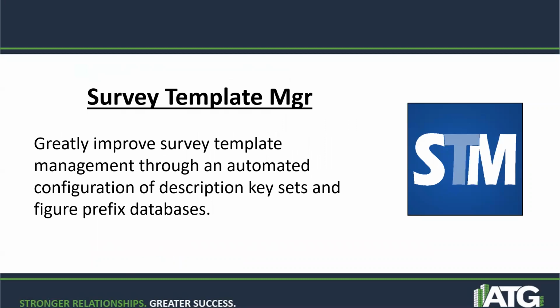First up is the Survey Template Manager. What this does is it greatly improves our survey template management through an automated configuration of description key sets and figure prefix databases. And we're going to do that by kicking all of the info we need out of Civil 3D into a spreadsheet editor and then sucking it right back in.